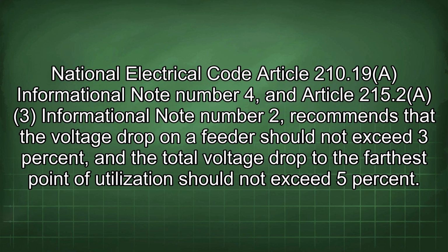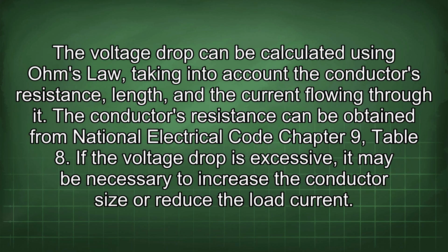should not exceed 5%. The voltage drop can be calculated using Ohm's law, taking into account the conductor's resistance, length, and the current flowing through it. The conductor's resistance can be obtained from National Electrical Code Chapter 9, Table 8. If the voltage drop is excessive, it may be necessary to increase the conductor size or reduce the load current.